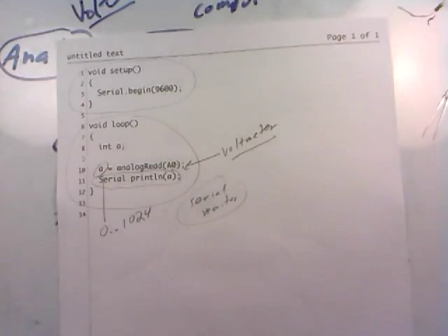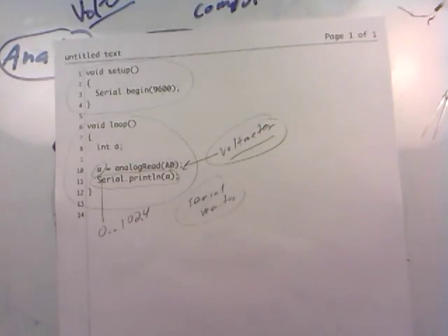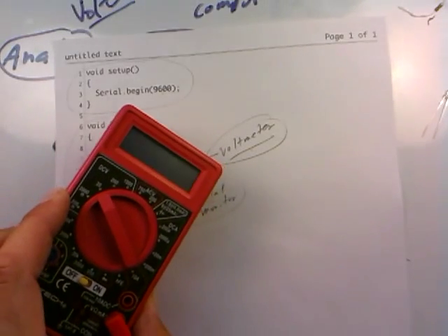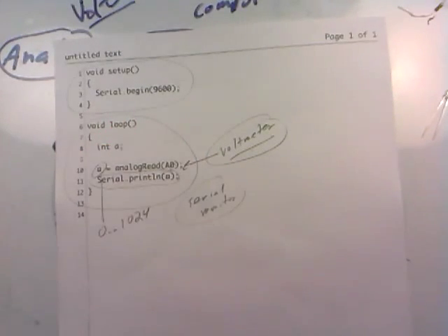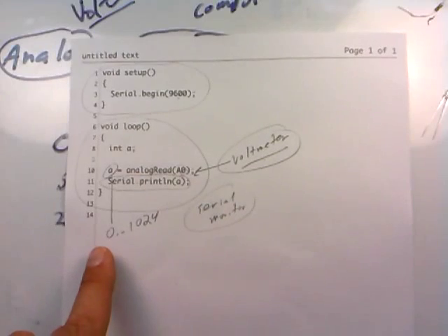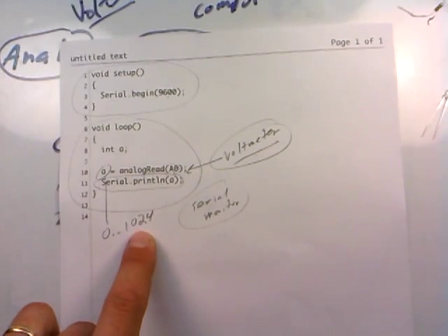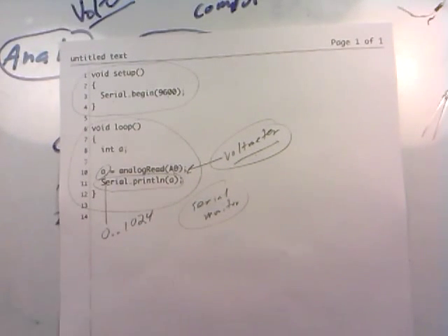That's what you get. Now you might be a little confused. I was like, oh, wait a minute, I thought the Arduino was behaving like a voltmeter. How come it's not giving me a volt? Well, it doesn't do that directly, but it's very easy to get at voltages. You can be rest assured that although these aren't actually the number that you would read on your voltmeter, they are numbers that are proportional to the voltage, because you know that 0 is 0 volts, 1024 is 5 volts. So any logic you might be thinking of implementing would work just fine.